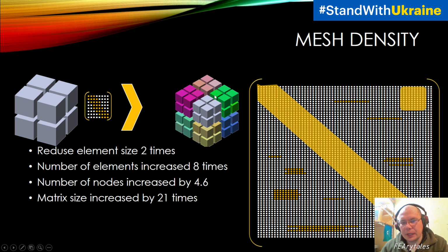If we use not hex elements but tetra, the situation can be something like that. And we need to understand that linear tetra has 4 nodes per element, and nonlinear or quadratic tetra, with mid-sides, or second order tetra, is the same. In terms of SolidWorks Simulation, high quality elements have 10 nodes. So it's 2 times more.